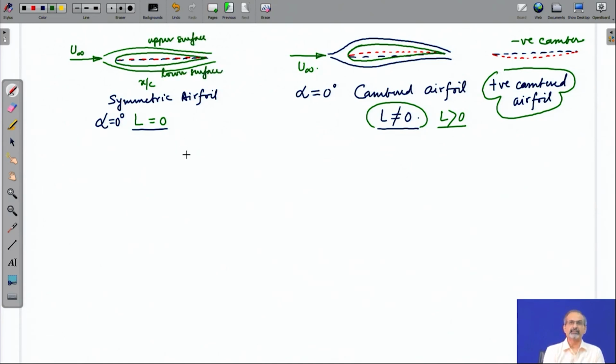One interesting thing is that if we are interested to look at the thickness of the airfoil and identify a location where it has maximum thickness, then it is easier done on a symmetric airfoil, because you can identify the thickness change along the length of the chord line much more easily because of the absence of camber. So, by careful observation, one may say that this may be the location of the maximum thickness.